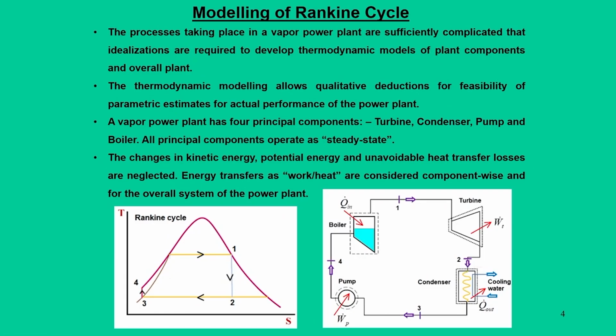In addition to that, we also have to see that the heat addition process in the Rankine cycle is increased, because in the heat addition process there are 4, 5 and 1. In this heat addition process, at constant pressure, that is, in a TS diagram under constant boiler pressure, the heat addition goes from 4 to 5, and from 4 to 5 we are essentially adding heat to bring the state of the liquid to the state of saturated vapor at point 5.